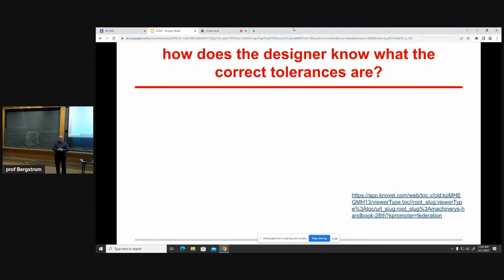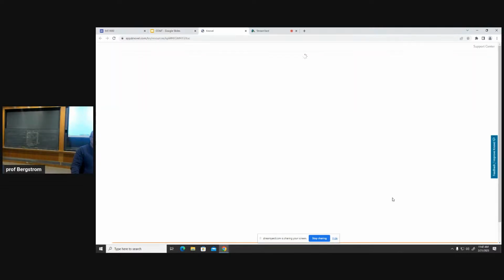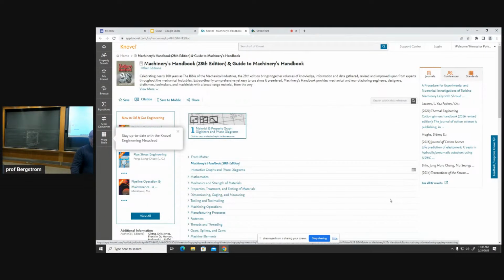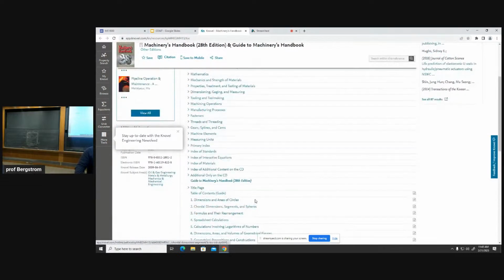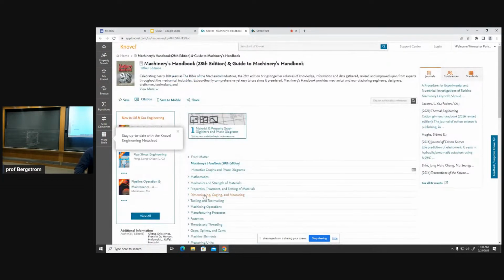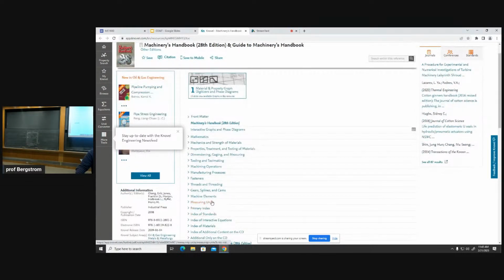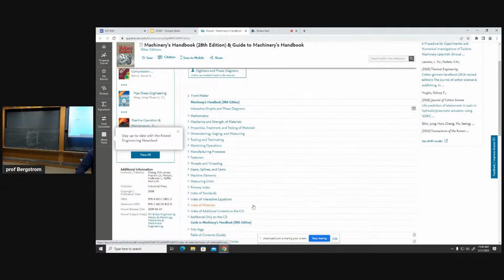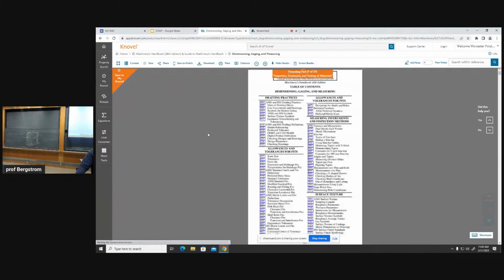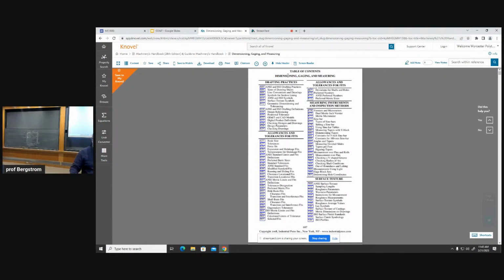Yeah, so to find things like press fit, there are manuals or websites that you can use that are pretty cool. You can go to the Machinery's Handbook. I think we showed you the Machinery's Handbook earlier in the class. What's the section called? So in the GD&T section, you go to allowances for tolerances and fits.